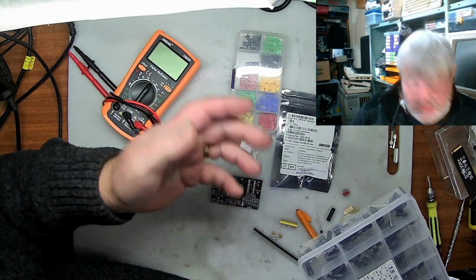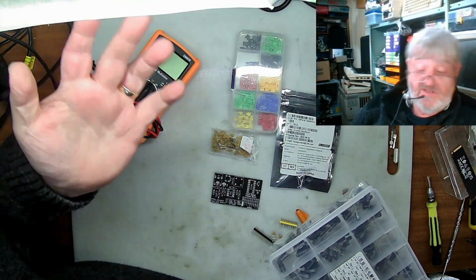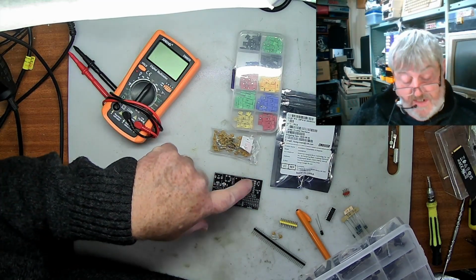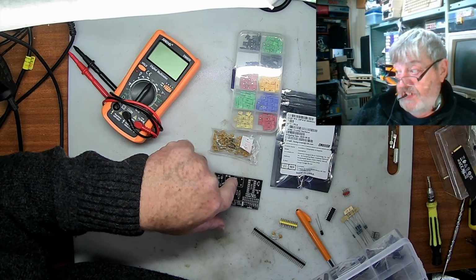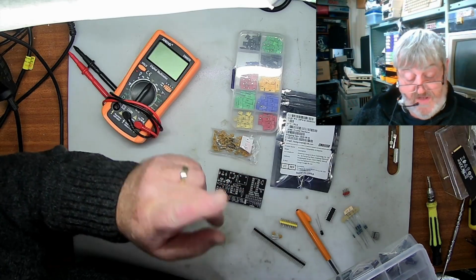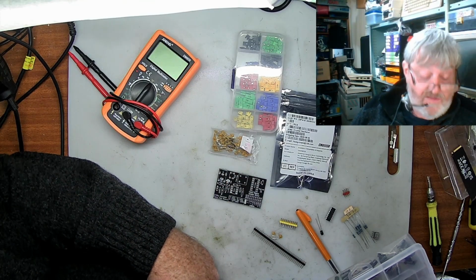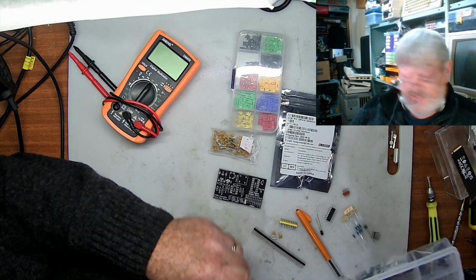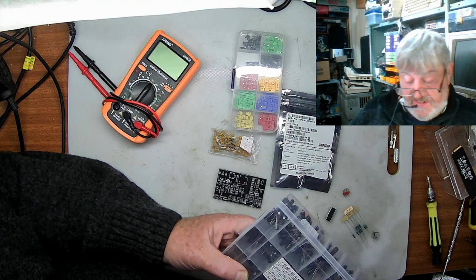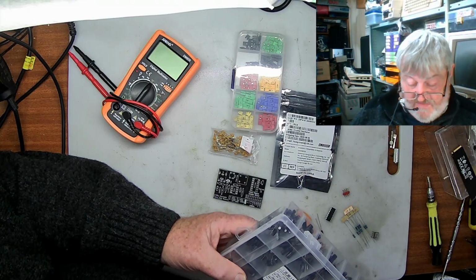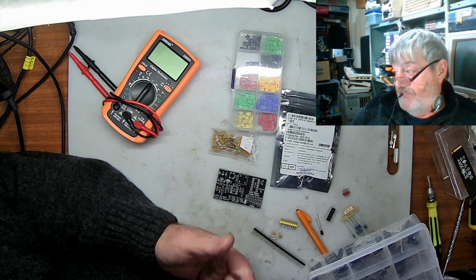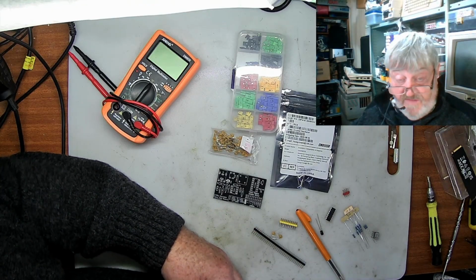If the capacitors go bad in a year or 2 years, I replace them, or build a new board. So the only thing I might put a socket in for is the crystal. I'm not 100% sure there, but I think that might be a good way to go. And yep, so that's it. So we've got our capacitor there. I'm putting a 25 volt one in. That's the smallest voltage I have in these electrolytics, so that's what I've done.